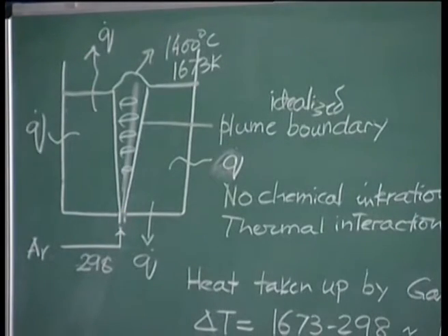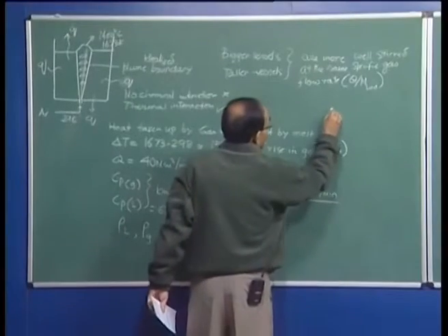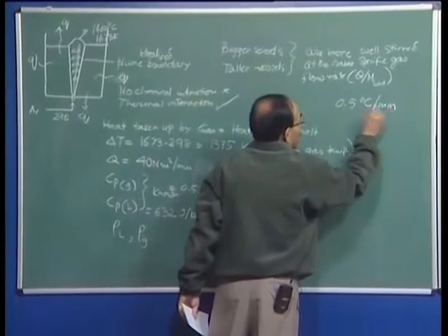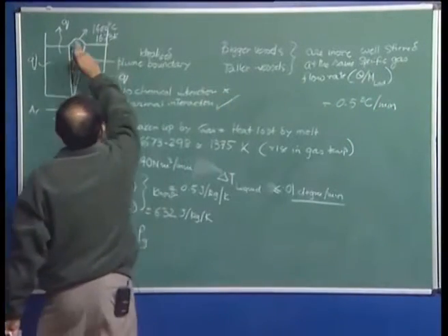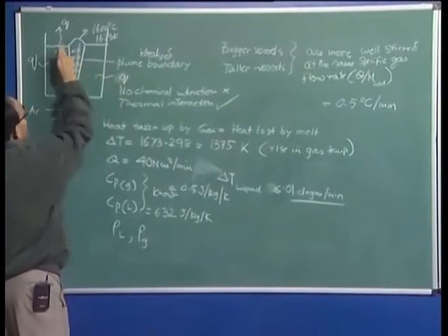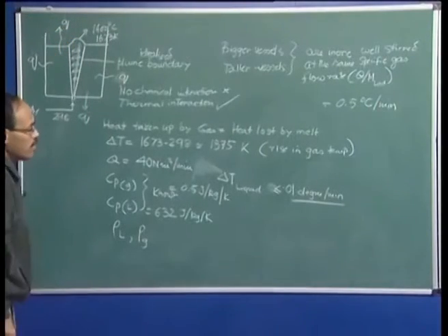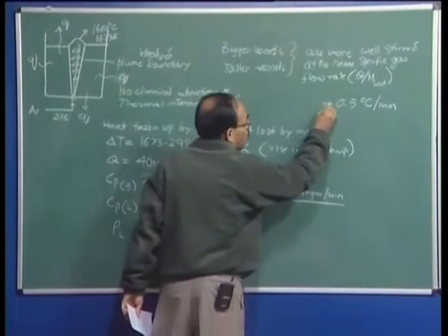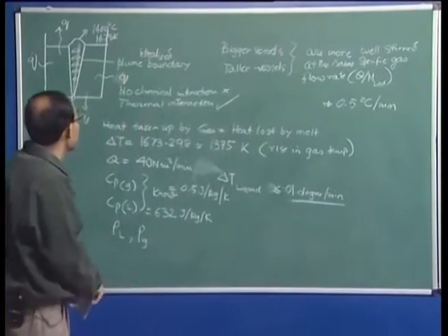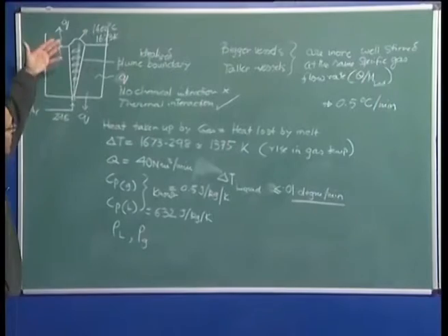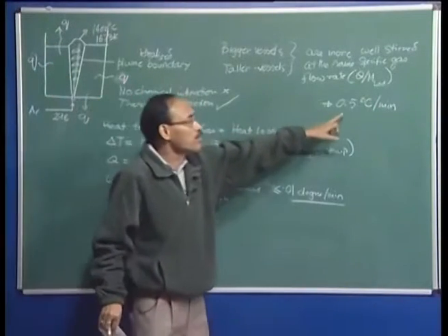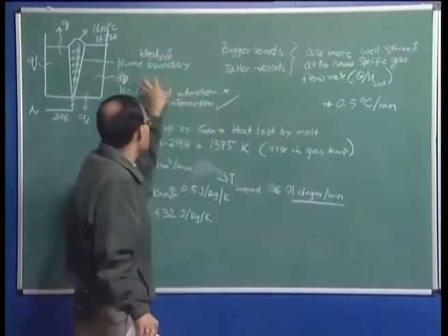And I think I have given you the value that for holding, due to the heat fluxes prevalent through the refractory wall as well as the slag lined free surface, the drop in temperature of the melt is of the order of 0.5 degrees, which essentially means that if we gas stir a ladle for about 30 minutes, there will be 15 degrees of drop because of loss of heat